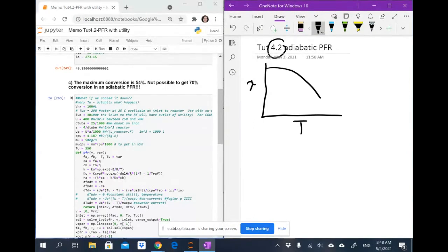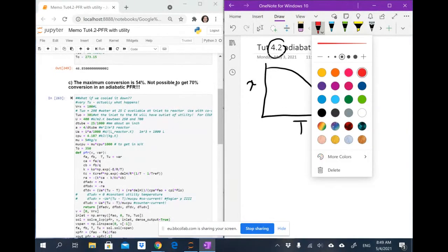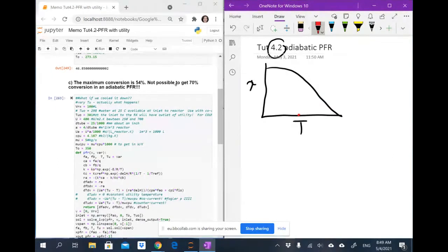So we could draw our equilibrium line, and I gave you specific inlet conditions, 320 Kelvin. That was the inlet condition there, and then we saw that the limiting conversion, my line is not perfectly in line, but regardless of what reactor type I use, if I operate adiabatically, I cannot go beyond this equilibrium point, right?